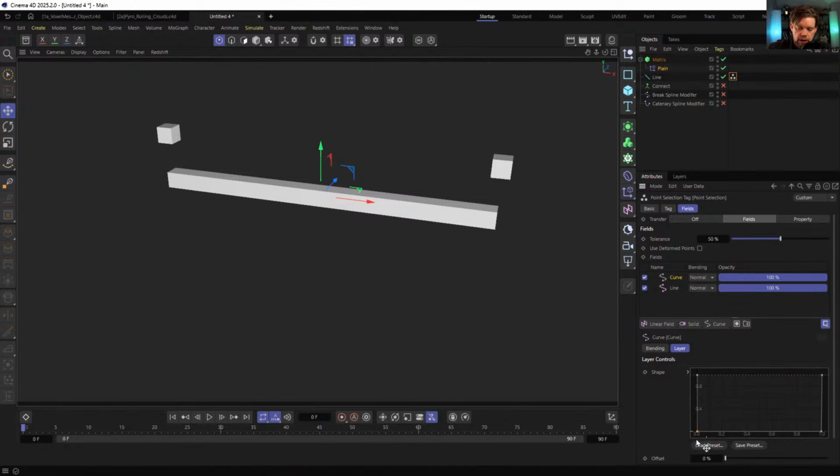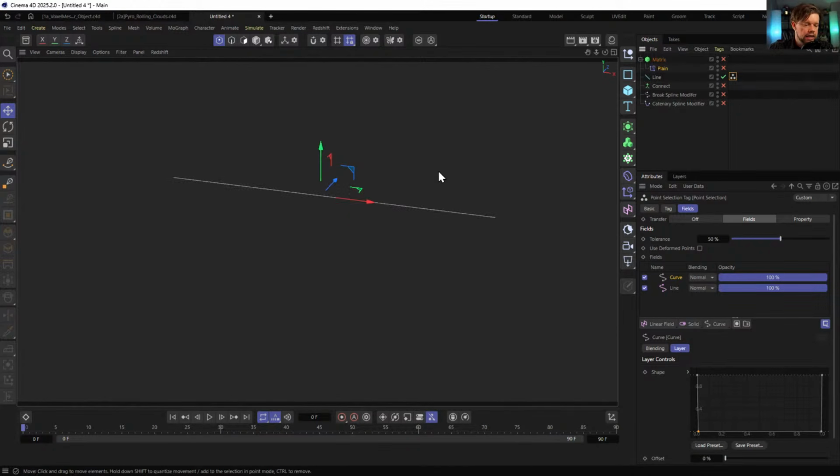But keep in mind, there's an inverse idea of that. And that would be if I subdivided this line more, let's say instead of 100 segments, there's 1,000. That would mean this point has to be less than 1,000th the way over, or another point would get selected and caught up in it. So just keep that type of thing in mind. But I now do have a parametric selection tag that is successfully propagating up through this matrix object. And this matrix object was just to validate if it seemed to be giving us the information or not.